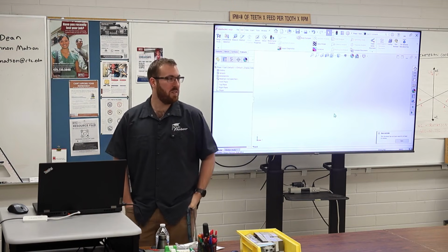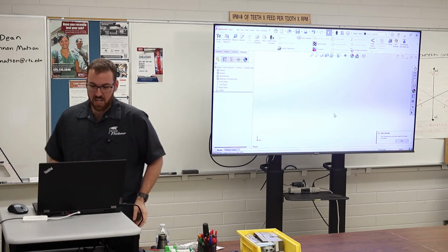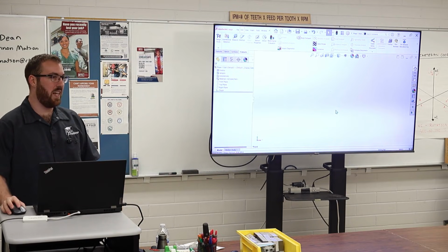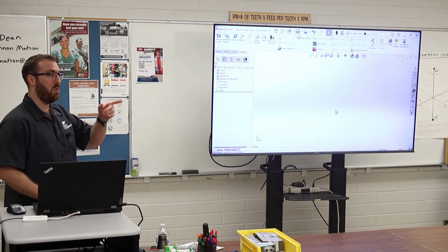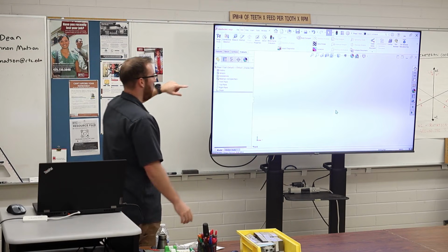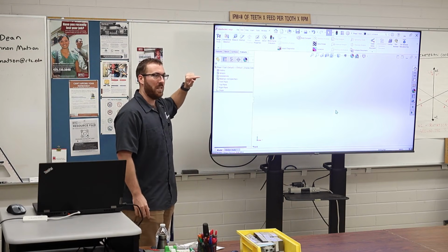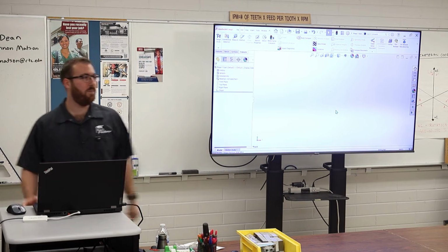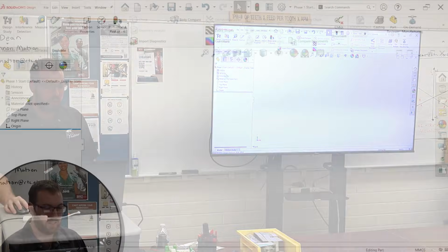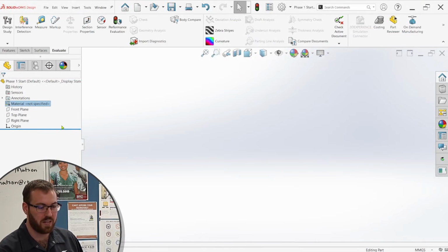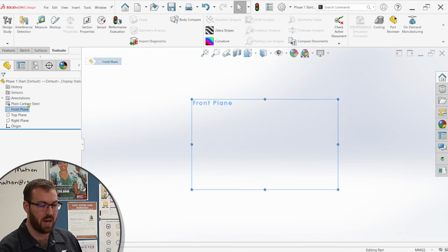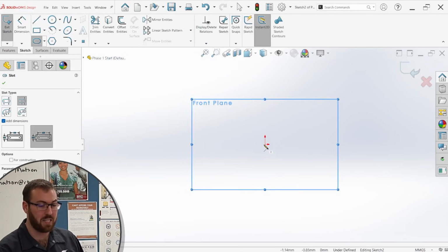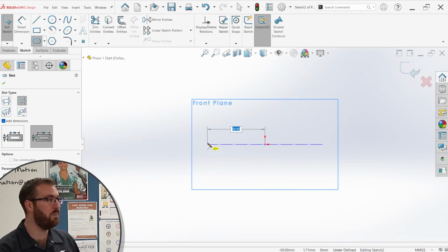Material. You've participated before, haven't you? It is so sad to lose because you forget to select a material. Now, question for you guys. Do you know what density is used when a material is not selected? Water. Kind of an interesting little fact there, but we're using plain carbon steel for this example. Our units are set, our material's set. Let's go back and sketch that out again. So that's the first thing I always recommend doing.